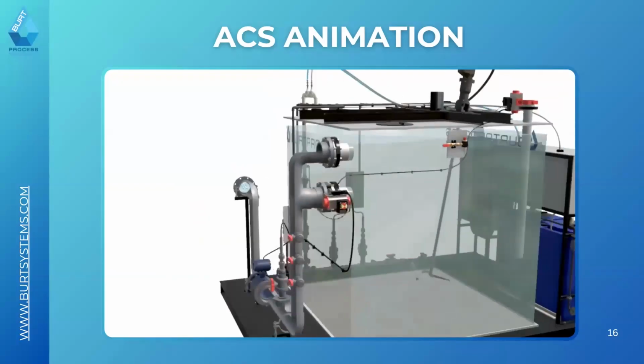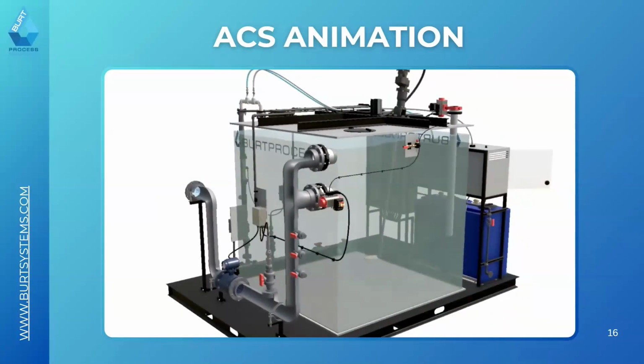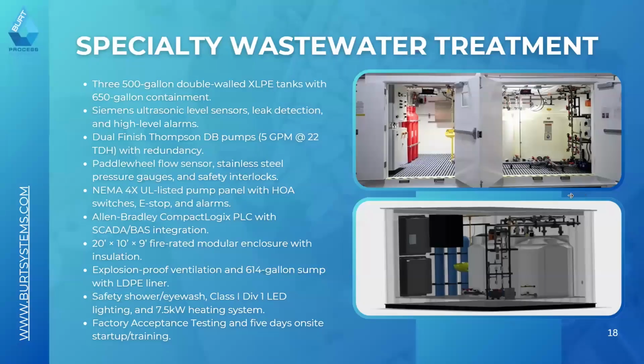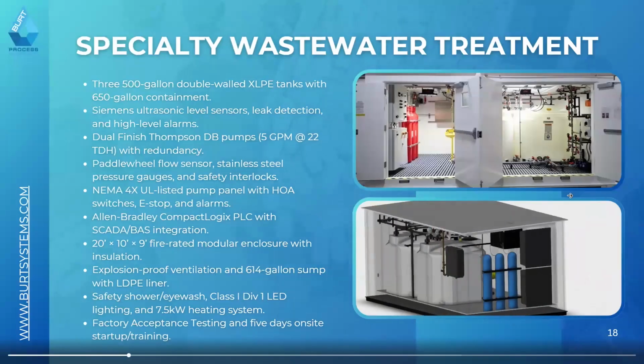There's a little model that's been running in the background while I've been talking. This is how a pH system operates. You can see the reagent injection, we have our treatment tanks here, overflow, and there's your monitoring and recirculation lines. So this gives you a very visual sense of some of the things I've been talking about today, and how they flow as part of the pH system. Just a few highlights here, because obviously we just talked a lot.